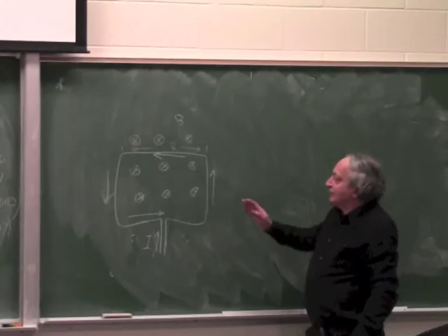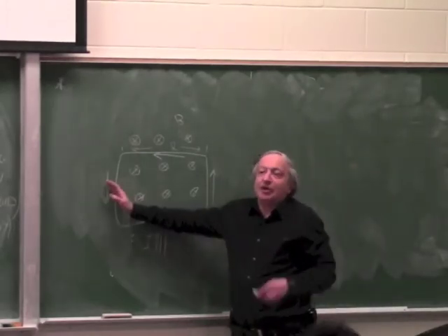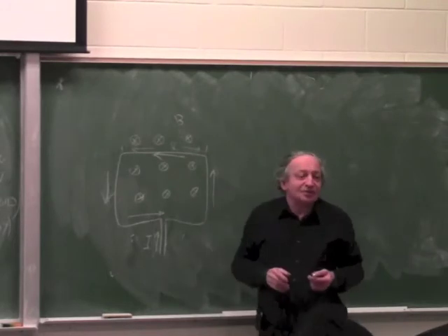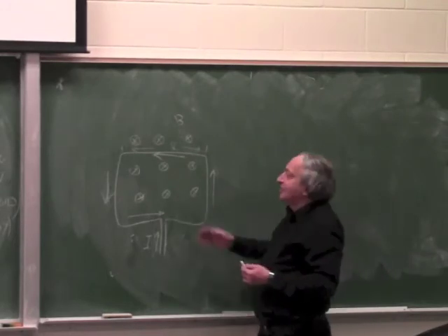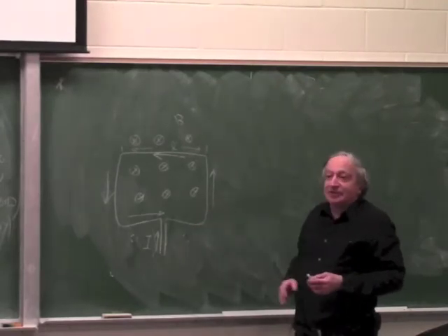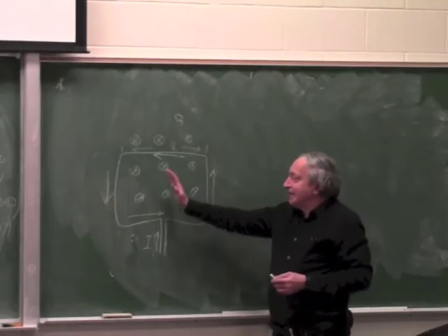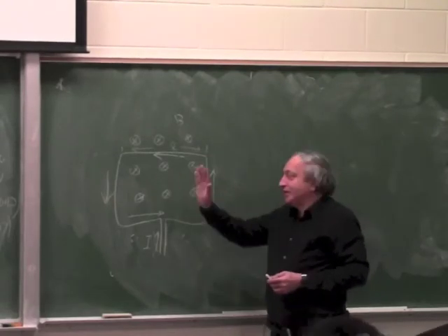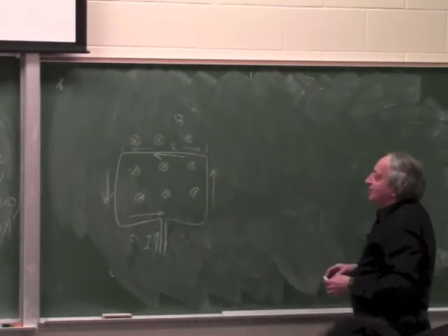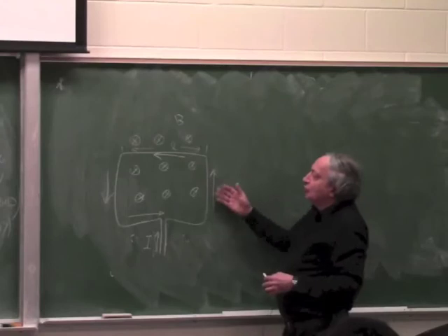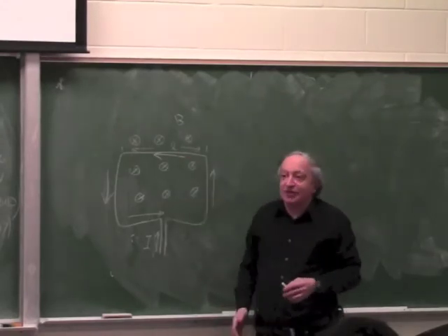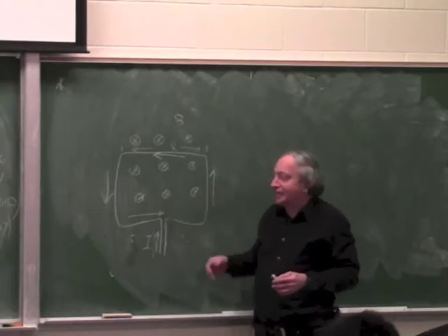So obviously, the forces on these two arms will be equal and in opposite directions. So obviously, if the whole loop is in a magnetic field, it will never move. Okay? In this position. If the whole loop was in a magnetic field in the other direction, you'll get a torque. Okay? So let me just draw that. Imagine now, so this is a loop which is perpendicular to the magnetic field, where the whole loop is in the magnetic field. Obviously it can't move. All the forces cancel out.